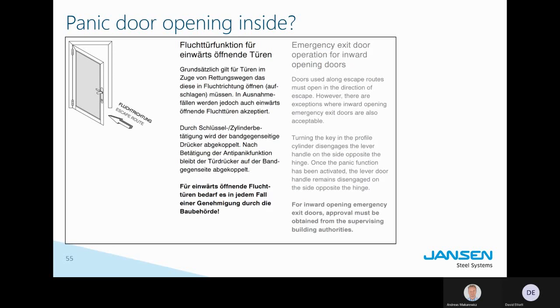In those cases, sometimes the door will open towards you. You have to pull it. Those cases are special cases. They always need to be discussed with, here in Switzerland, the fire department. They approve this type of opening. It's an exception usually. Panic doors or panic/fire doors usually open in the escape direction.